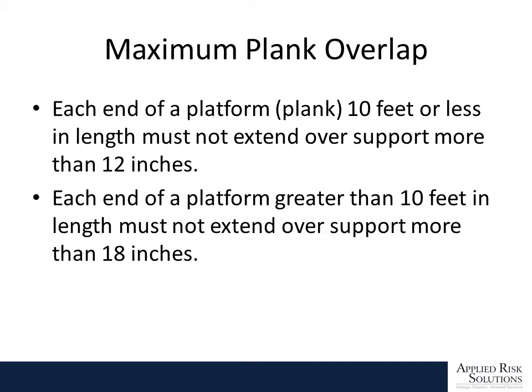So remember, you get a minimum of 6 inches and a maximum of 12 inches if your boards are 10 feet or less. If they're greater than 10 feet, you can overlap by 18. So it's either 6 to 12 or 6 to 18 is your range you have to be in, depending on the length of your board.